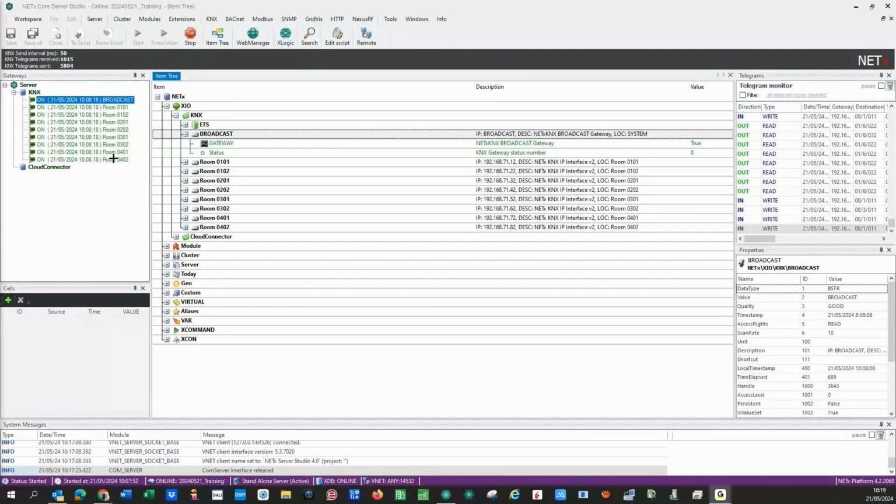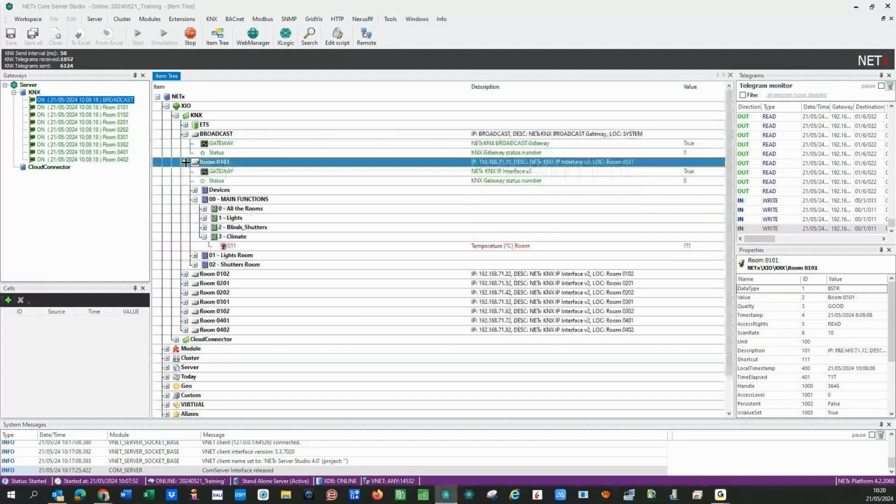But we don't have only KNX. Remember, we have a BMS connected to all the installation. So the broadcast driver is helping us to do this job. It's possible to define one item that you have configured, of course, in the actuators. You need a specific group address that is also configured in the actuators, and do this job. Send a telegram to the IP tunneling connections simultaneously. It will send to all of them.